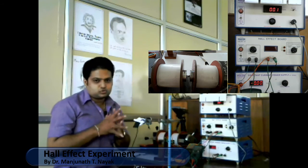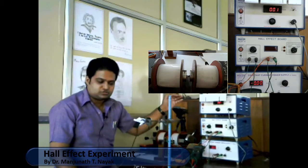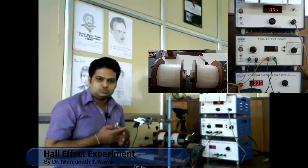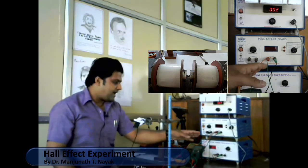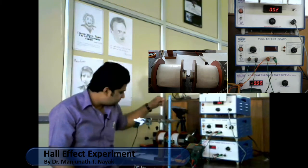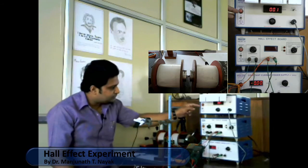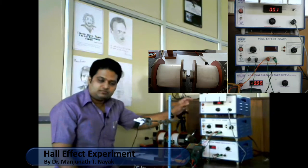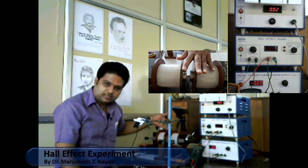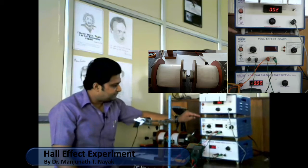This experiment has two parts. First, for a given current, how much magnetic field is generated. We give current of 0.5, 1, 1.5 up to 2.5 amperes, and check how much magnetic field is generated in the Gauss meter using the Gauss probe, and note it down, because in the second part we are not going to check the Gauss meter reading. We are going to only set those currents, and that much magnetic field will be generated in the electromagnet.